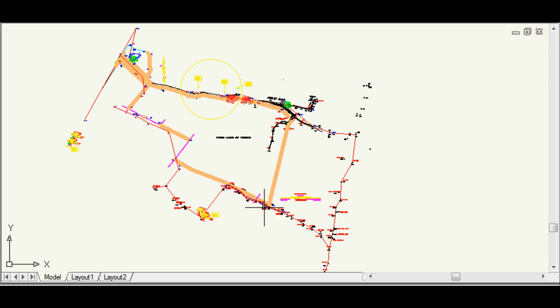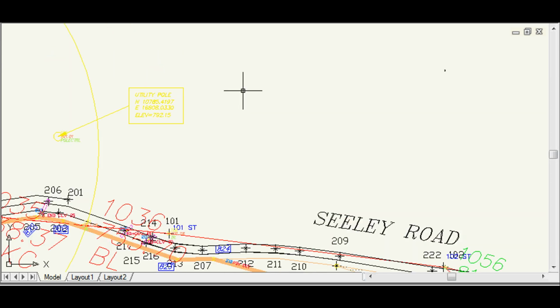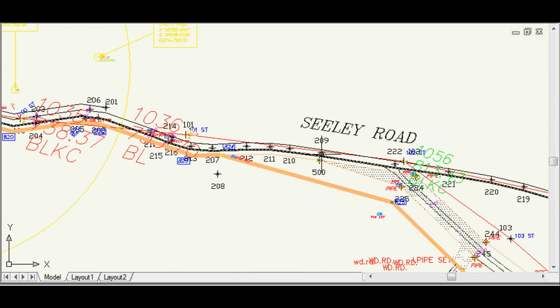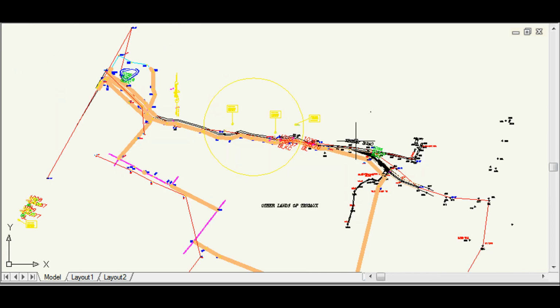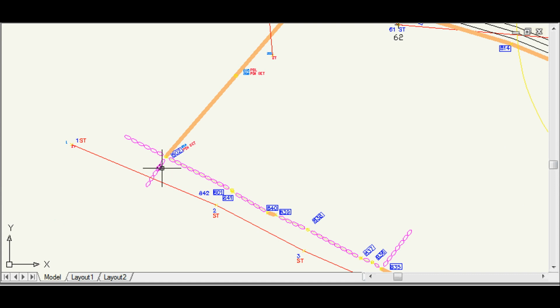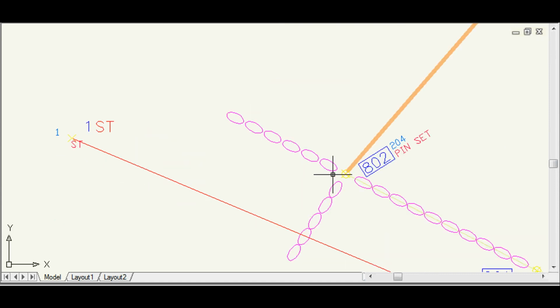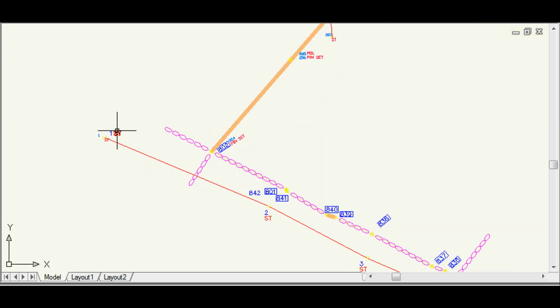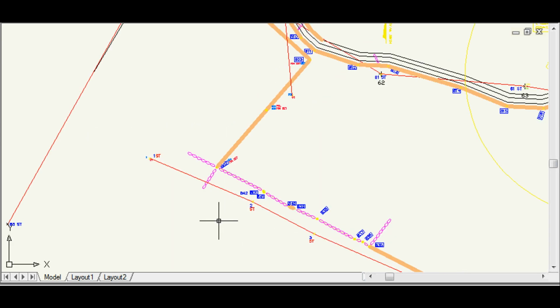And then once we have something we can count on and take measurements from, when we zoom in, we go along a roadway or a stone wall, or we shoot in a pin, we can turn to that from one of these baseline points, like here, the stone wall corner, right? We can set up on this baseline here and shoot the stone wall corner. And now we know, because we've set up on the baseline, that we have solid controlled data.